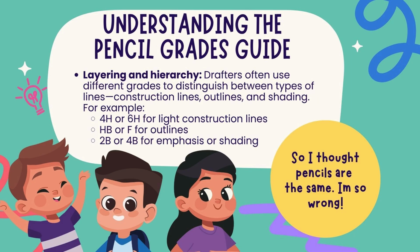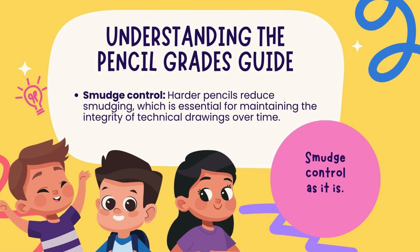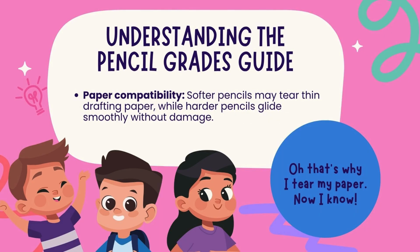For example, 4H or 6H for light construction lines, HB or F for outlines, 2B or 4B for emphasis or shading. Smudge control: harder pencils reduce smudging, which is essential for maintaining the integrity of technical drawings over time. Paper compatibility: softer pencils may tear thin drafting paper, while harder pencils glide smoothly without damage.